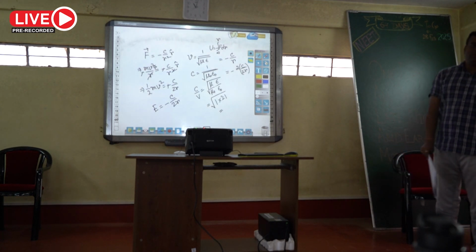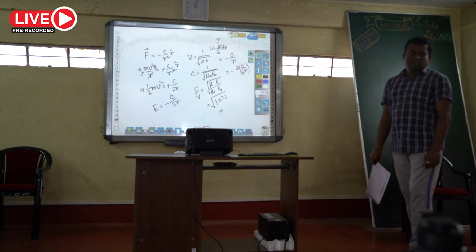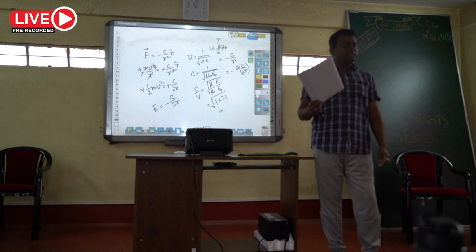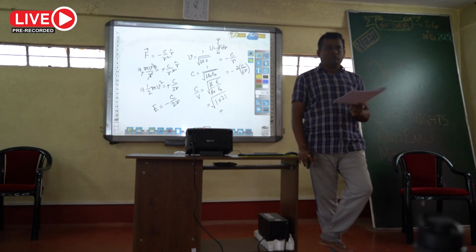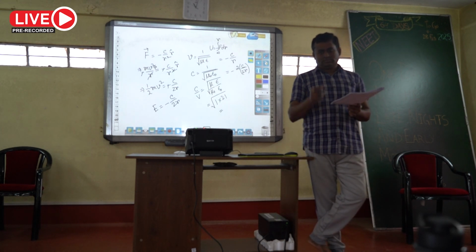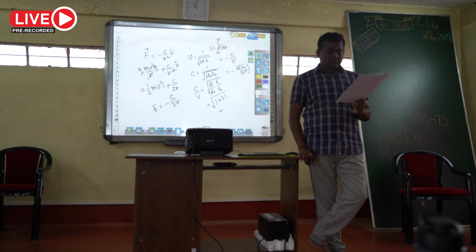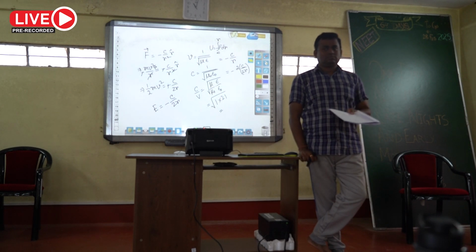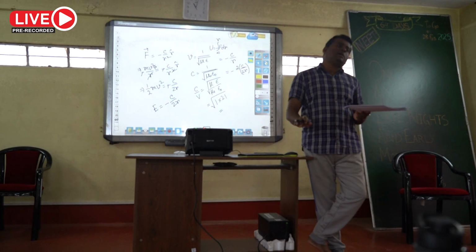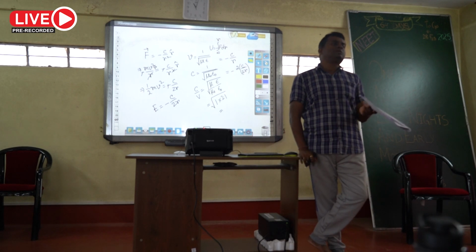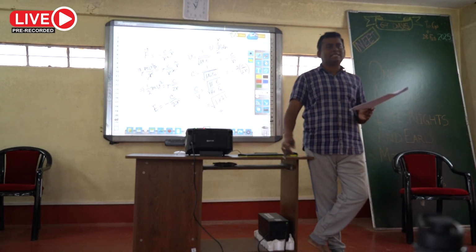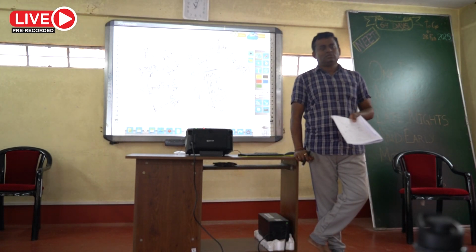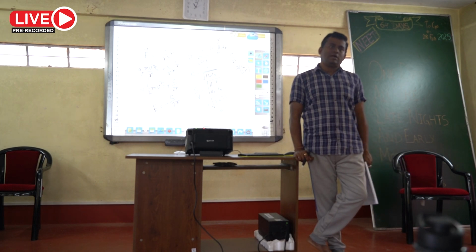That is, 200 volt is given as the RMS. So peak value is coming in the output. Because in the other half cycle it may be 0 because of the half wave rectifier. But in one half cycle, what will be the value of the voltage across the capacitor? So only the peak value will come.